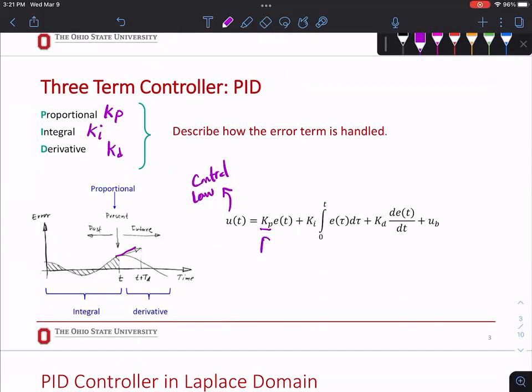So this is your proportional control. Plus your KI times the integral, the area under the curve before that point, so the accumulation of all the error in the past, right? So you're compensating for all those errors. That's the I part. Plus KD times the derivative, which is the tangent, right? The derivative tells you what will happen in the future, or can estimate. So these are the three parameters of the PID controller. That's it. That's the rule of the PID controller.